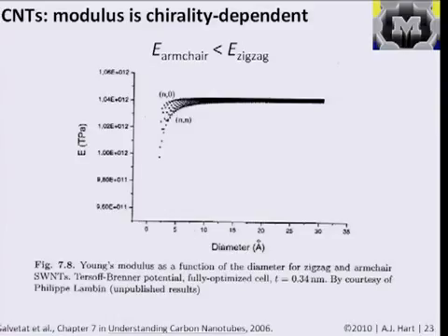But I think it's interesting to think about this effect, that the built-in deformation of the material can affect its mechanical properties. And these are all done by some computer calculations where they used a particular potential function called the Tersoff-Brenner potential, named after the guys who brought it up. This is basically a potential function like the potential curve we saw earlier, but more complex and represents the potential in some different dimensions.